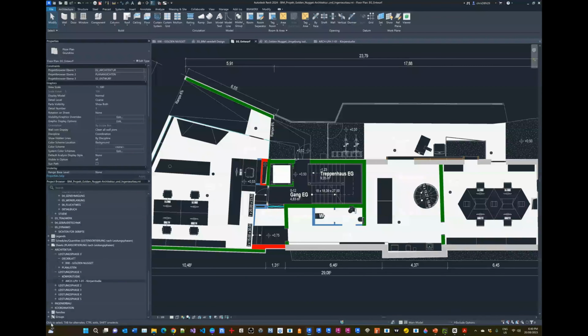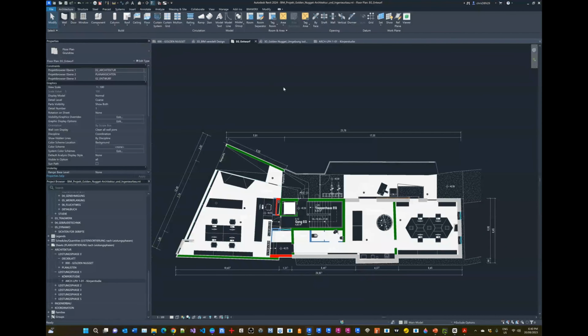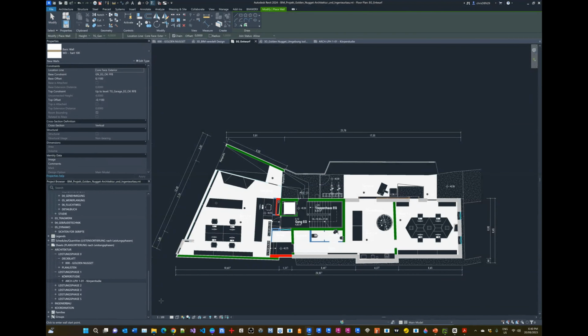Okay, and then at the bottom left, we have got the status bar. So this is telling us what to do in the model. So if I want to create a new wall, for example, if I initiate a new command, it's going to tell us what to do. It's going to say, click to enter the wall start point. But there is also another toolbar that appeared here just below the ribbon. And this is giving us some specific options for the object being created. It's telling us that there's a height property, there is a target for the top and the bottom. There's a location line. Do I want to start drawing from the center or the exterior or the inner face of the wall? Do I want it to be chained, in other words, continued? Do I want an offset? Do I want radiuses, etc.?